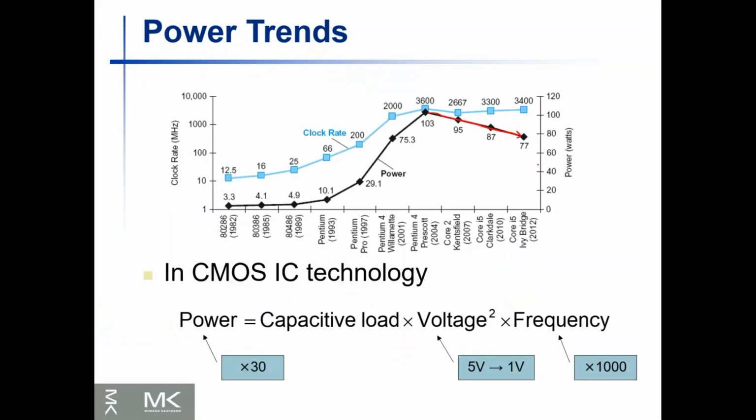Now, one of the reasons is the dynamic voltage and frequency scaling. Other than that, it is because of better process control. The other thing is more cores with lower clock rate, that's another strategy of doing things. So finally, power really depends on capacitive load, voltage and frequency. This actually impacts the total power consumption. Using a lower voltage will definitely help power consumption.